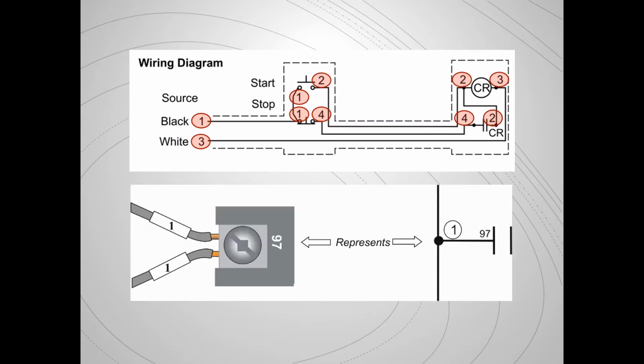When it comes to physically putting my wires underneath the terminal, even though I have two wires possibly going underneath the same terminal, I need to identify that as being a splice or connection. On my schematic diagrams, I would show it as a node, and I would be able to see on my wiring diagrams that when I have multiple lines going to the same connecting point, it's the same thing as putting multiple wires underneath the same screw.